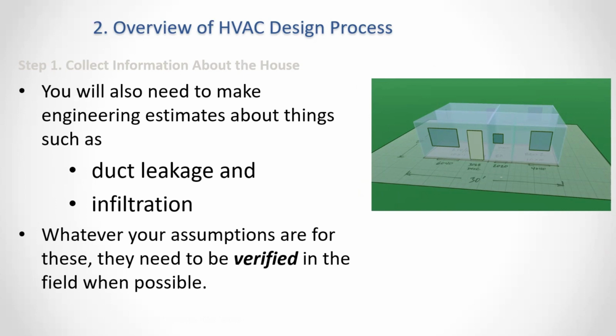All right, so there are a couple of things you don't get off a floor plan, and that's things like duct leakage and infiltration. How leaky is the house? Well, it'd be great if you tested that, but actually for duct leakage, it'll be tested later on, because in California we have a rule that says if you do HVAC replacement, you have to seal the ducts as part of that work, and you have to seal it to 10%. So 10% is a reasonable number to assume in your load calculation. All right, so that's pretty straightforward.